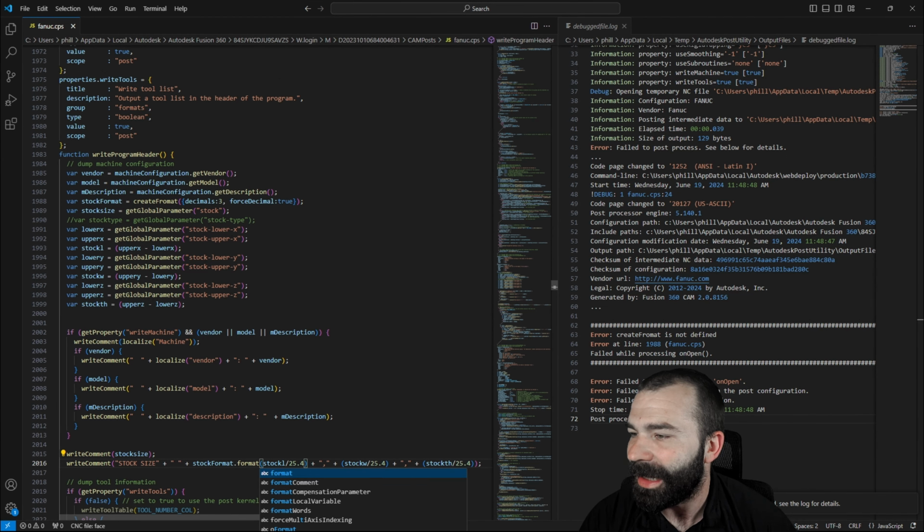So what I'm going to do here is I'm going to go ahead and jump back down to our lines of code. Now, what I'm going to do for this is we're going to go ahead and start to add more information below this line, right? So we have stock size. Now we're going to call our origin. So the first thing I'm going to do is I'm going to say if, and with that if statement, we're going to go ahead and say stock lower X, and we're going to add stock upper X.